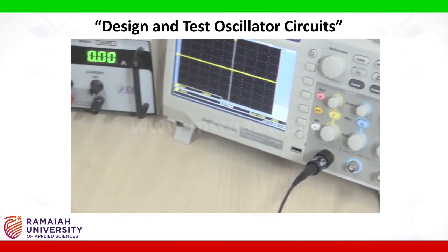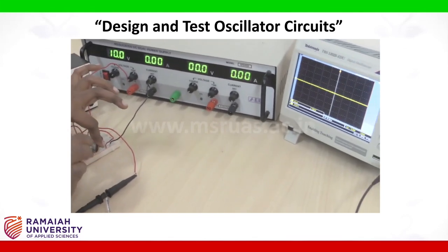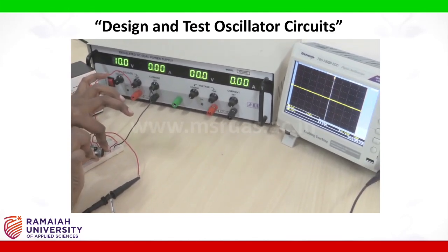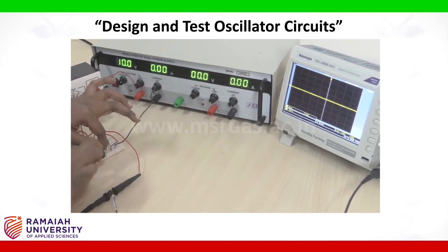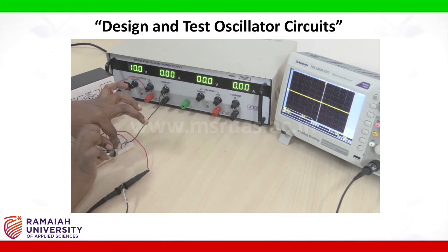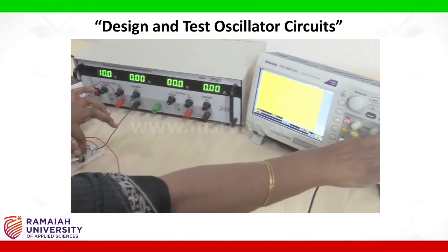Now start tuning your pot. As you tune the pot, continuously check the oscilloscope. Now press auto set if required.